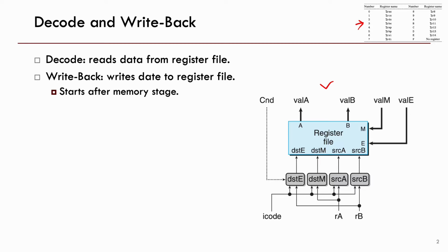So the decode stage will start whenever input data is available. Actually, when source A and source B are ready, then it will output. Because reading should be fine even with some unavailable input, right? It won't halt the implementation or corrupt register values just because it is reading in the decode stage. So it is okay to start as soon as input comes.